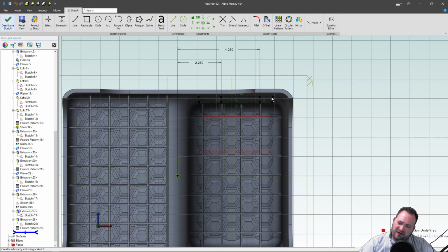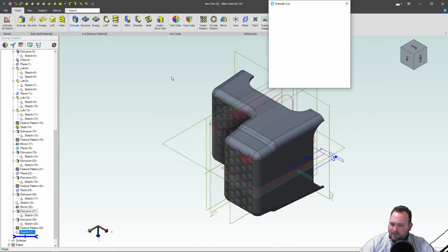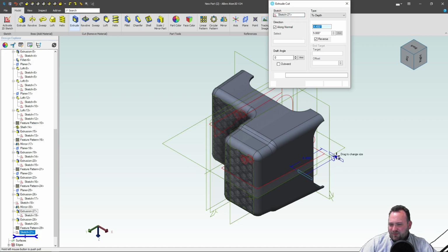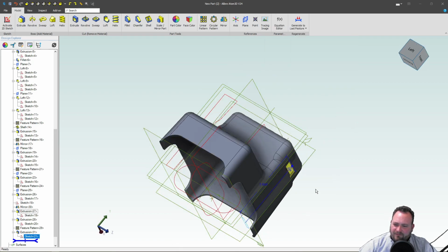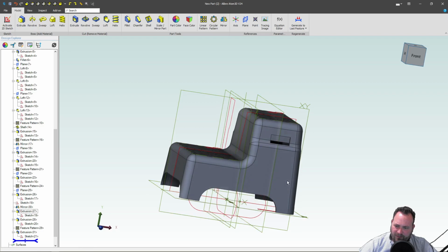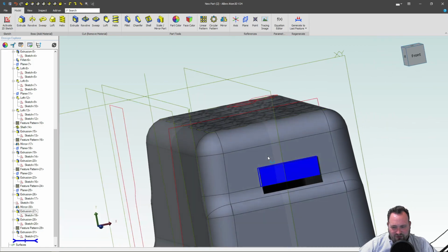Right, so we're taking advantage of the fact that we have a slanted face, and we can cut straight up. Again, these rebuild times are catching up with me, so I'll have to resuppress a few components. All right, let's say okay to that. And just see where we're at, because I think we have a few things to adjust. But yep, so there we are, cutting with draft. You can tell we went straight up and down, but because the face is curved, we were able to make a cut through there, and also our tooling can go straight up and down at that point, and we can just cut away the draft like that.